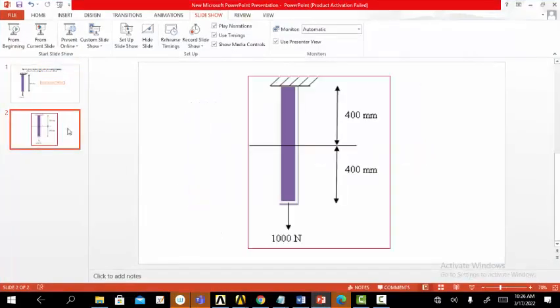For following finite element analysis to solve structural problems, we have to subdivide the entire structure into a convenient number of elements. We have to divide the entire element into at least 2 elements for performing finite element analysis. For that I have subdivided the entire cantilever bar into 2 elements. Exactly, I have split the entire element into 2 equal halves.